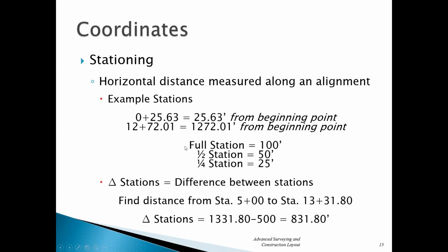And when we hear the term full station, half station, or quarter station, that's an interval based on 100, 50, or 25 feet respectively. What was the interval that we staked our curve out last week? Anybody remember? 25 feet. Yeah, which is very standard, particularly on highways where you're doing curb or even just edge of pavement, just stuff that doesn't even have a curb. You're going to do it like usually every 25 feet. So you guys should think about that and appreciate that.